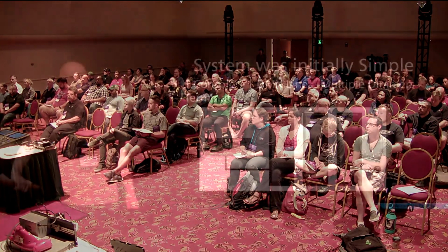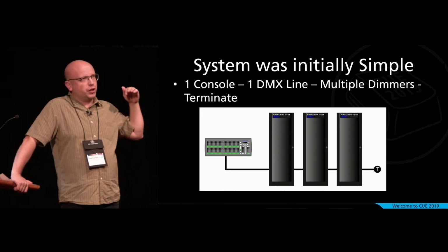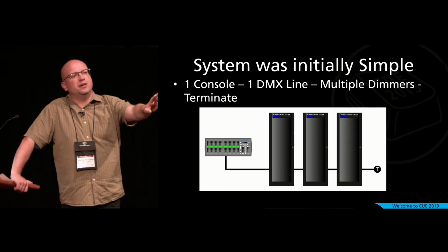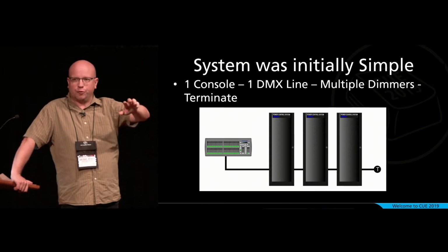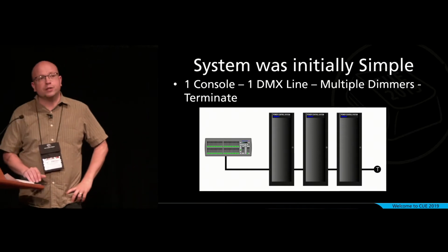Doesn't bounce back. Yep, that's right. You can kind of think of electrical signals in a cable like a wave. And what the terminator does is provide a nice end so the wave stops there rather than hitting the end and bouncing back again. That's called a reflection, and it can lead to weird signaling problems. So always terminate your DMX line.